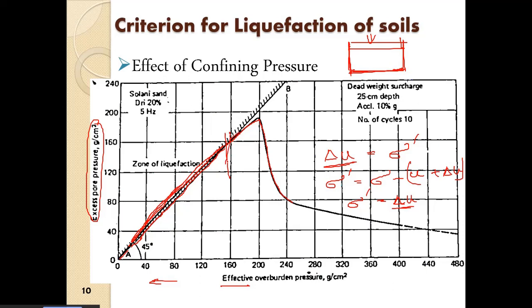Then from a particular point, and in fact after a certain state, we see that the development of excess pore water pressure is negligible, and there is no chance of liquefaction whatsoever. Right? So it is only in the lower confining pressures, in a certain range of effective confinement, that there is a chance of liquefaction. In fact, this also correlates well with the flow liquefaction surface.